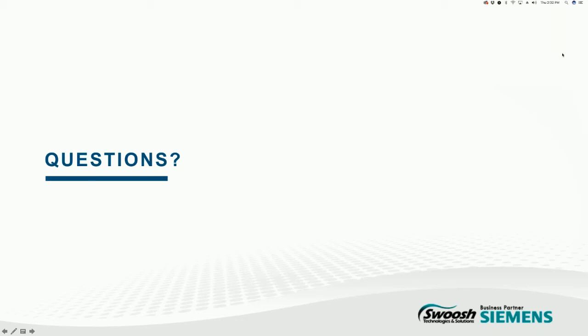Okay, great. We also have one that says, I missed the step where the settings are in Solid Edge and how to turn on the built-in tools. Oh, okay, yeah. It actually took me a while to find that myself. All right, so inside of Solid Edge, you can be on the splash screen or within a template, doesn't really matter, but it's the application button, and it would be application, settings, options, and in the options tab, you have a manage field. So you go to manage and just toggle that on, and then you have all the settings to predefine right there. But toggling that little switch is what turns on the fast search for Solid Edge.